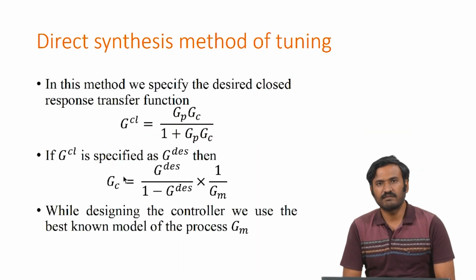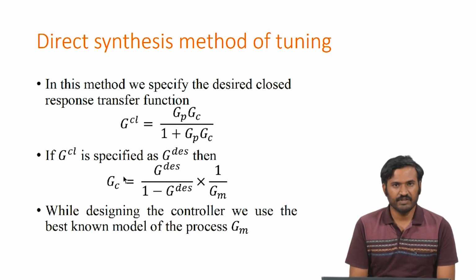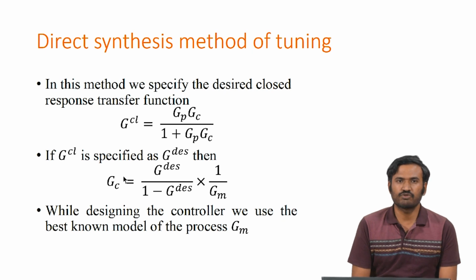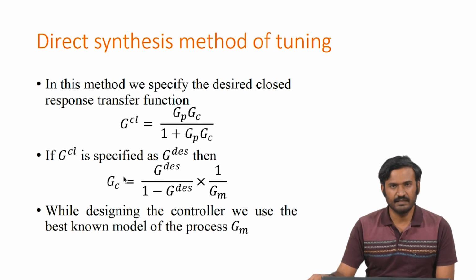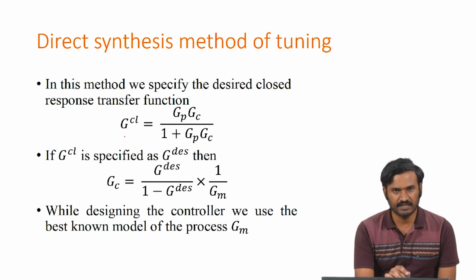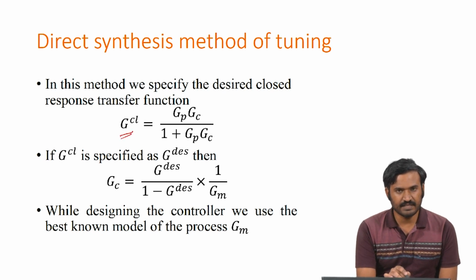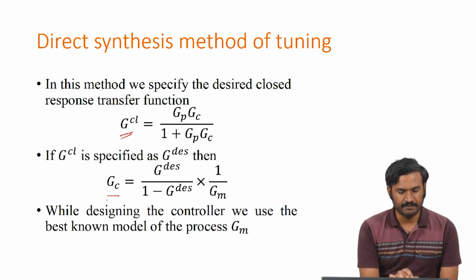In this method we have the direct synthesis method of tuning, where we specify the required closed loop performance in terms of GCL. As can be seen in the closed loop transfer function, we can specify GCL and ultimately back out GC.